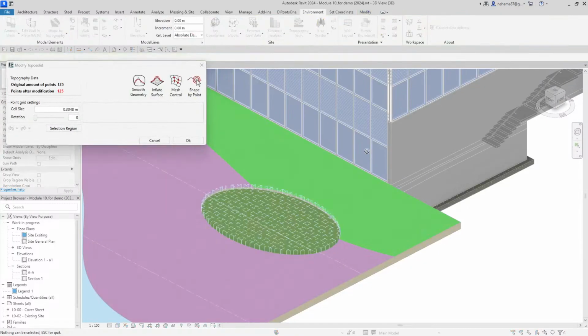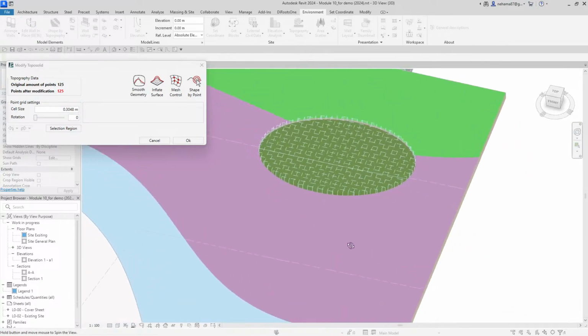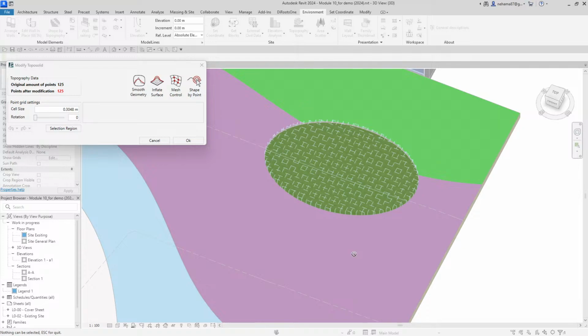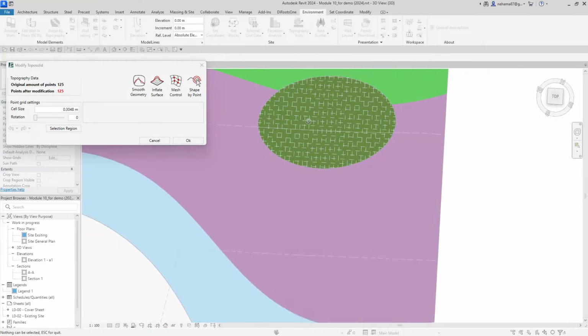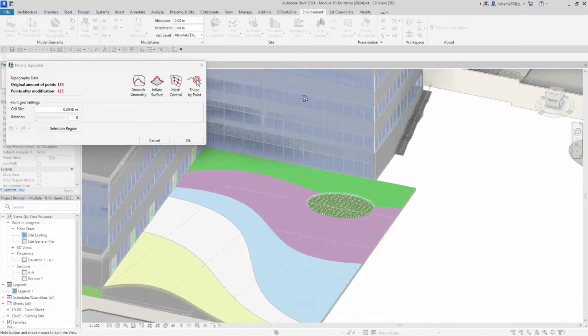And if you guys don't know these tools, I think it's one of the nicest things that we have here in environment. These are basically a bunch of tools that are meant just for sculpturing the landscape. With the topography tools, we were talking about a specific strategy for every point that we're placing. Here you can see this grid that I have on my surface. I'm actually going to place a grid of points on top of my surface to make a very, very smooth